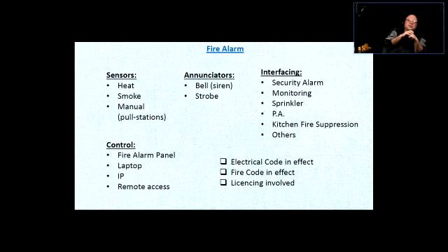So first in the kitchen suppression, an oxygen suppressant is released onto the plate, but since the plate is still hot, the fire could reignite. So first, the oxygen suppressant puts the fire out, and to avoid the possibility of reignition, water is spread in order to cool things down. That's the usual operation of that. And the others, I just put that because it's a good idea. Makes me look smart, right?